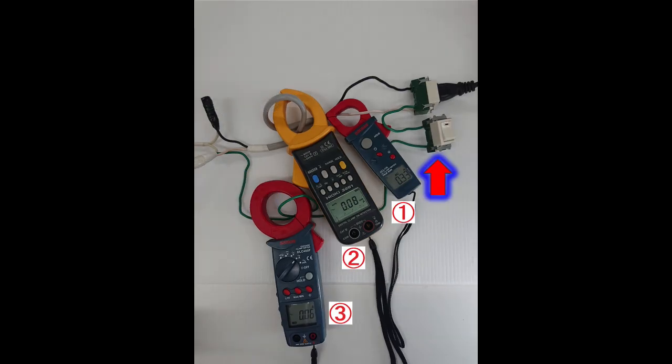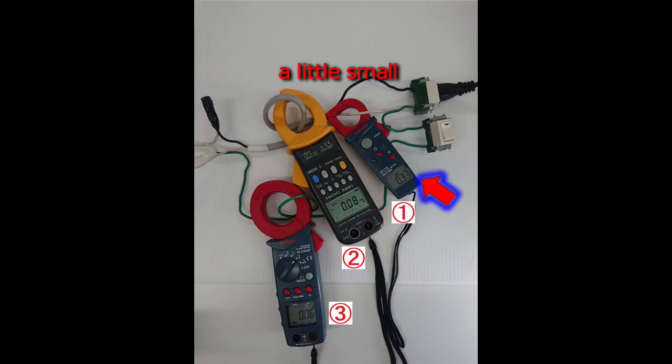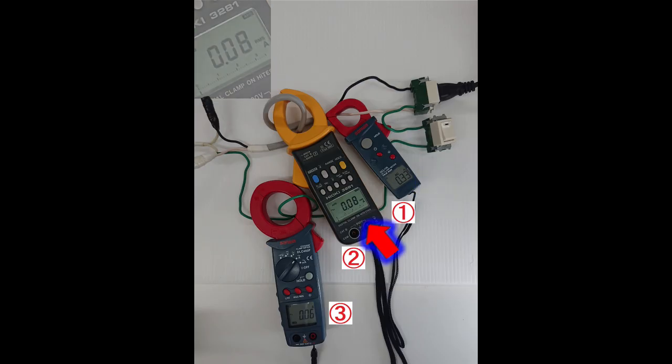The next photo shows the earth leakage circuit with the switch turned on. Clamp 1's electricity has been reduced from 0.44 amps to 0.33 amps. This is because the amount of electricity flowing through the leakage circuit has decreased. For clamp 2, the electricity has increased from 0 ampere to 0.08 ampere. This is because the electricity that flows into the lighting fixture is 0.44 amperes, but the electricity that returns is 0.33 amperes, so the difference is measured.